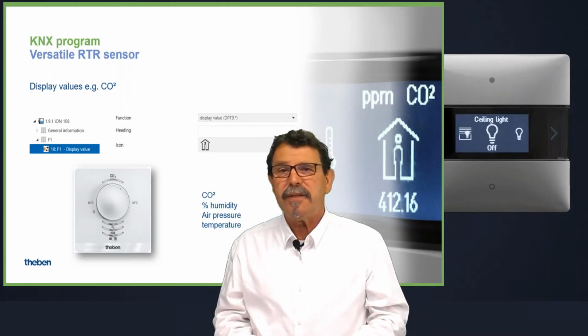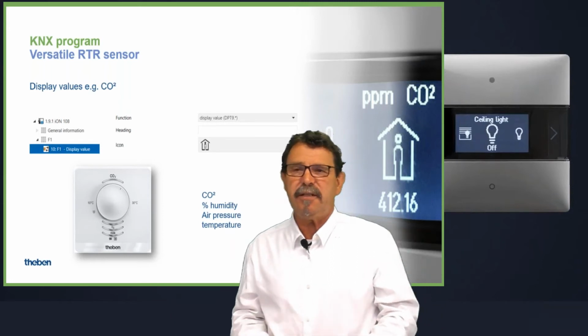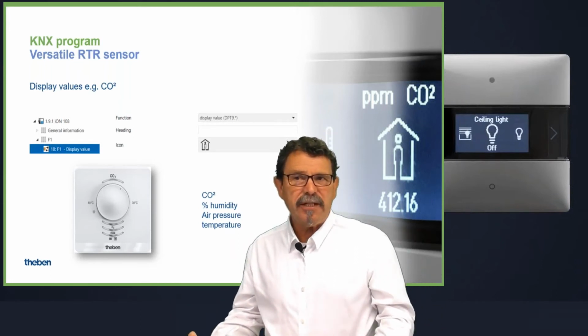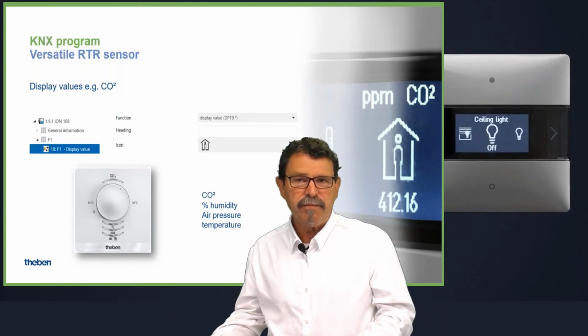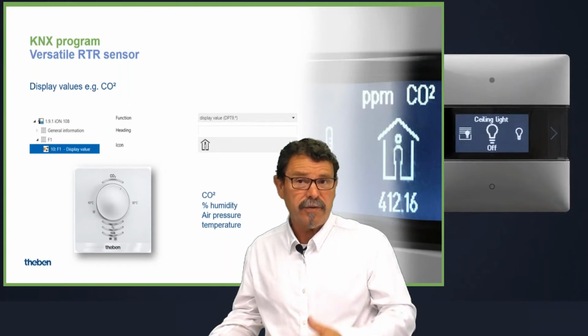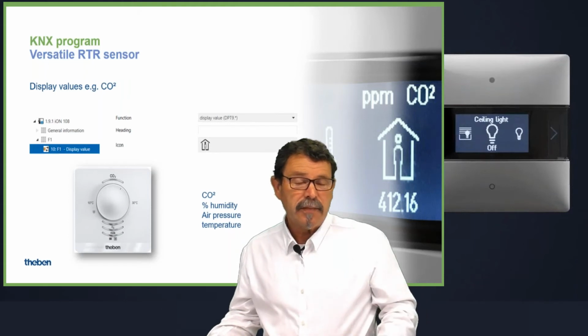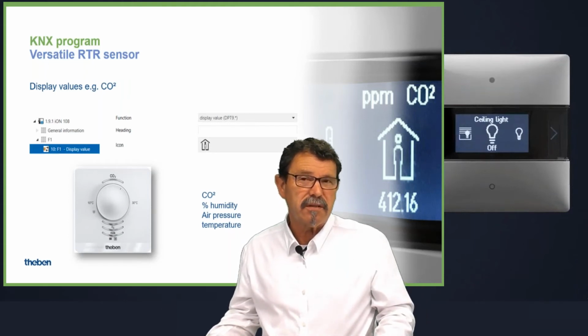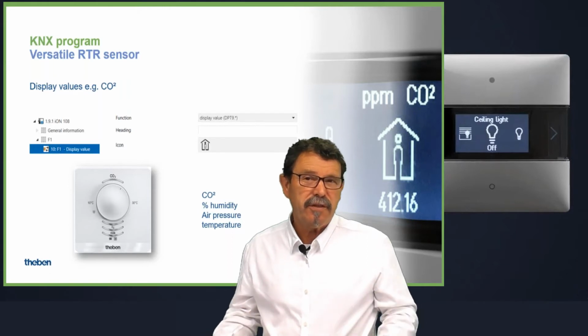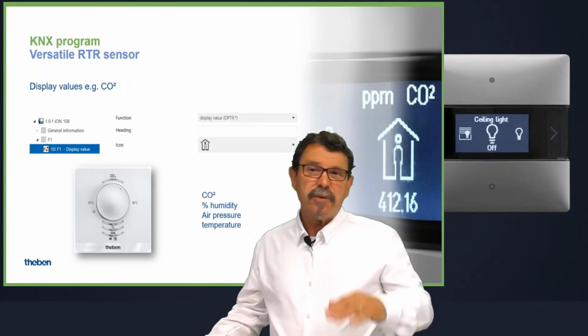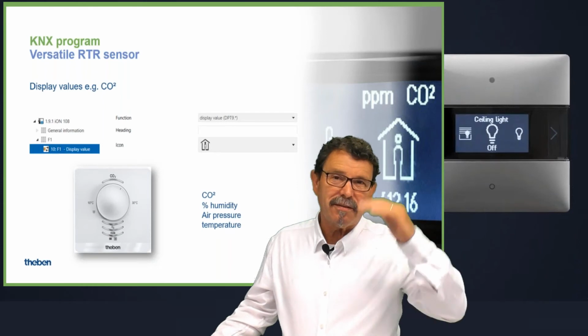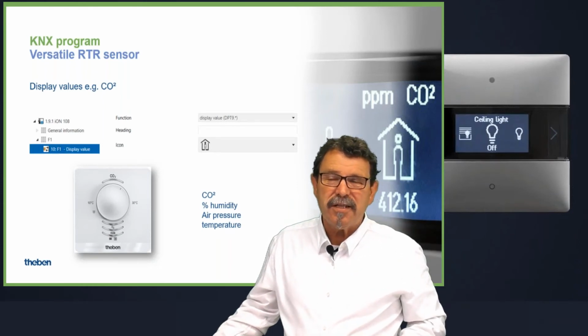Why air pressure? There is a short secret behind. There is a relation: measuring of CO2 is always related to the altitude over sea level of the installation. So that means when we, for instance, take into account, we do have here down Singapore or so, we are almost 10 meters above sea level, even less.